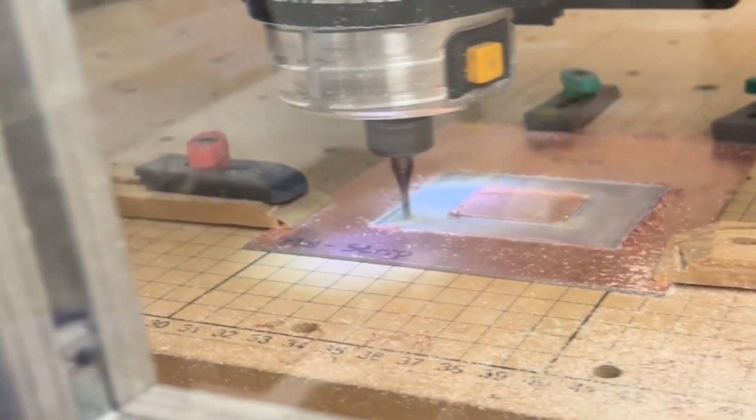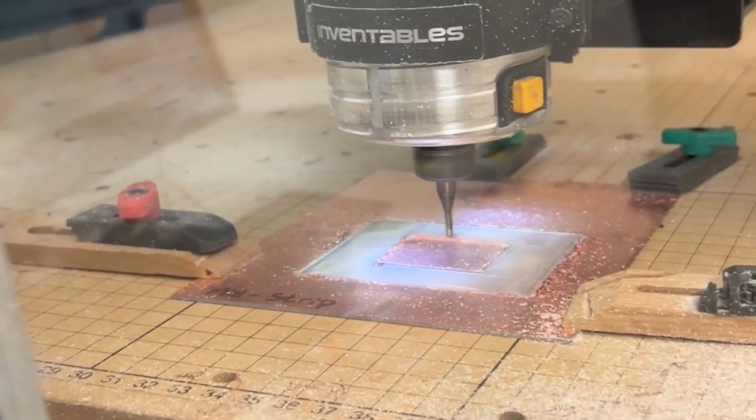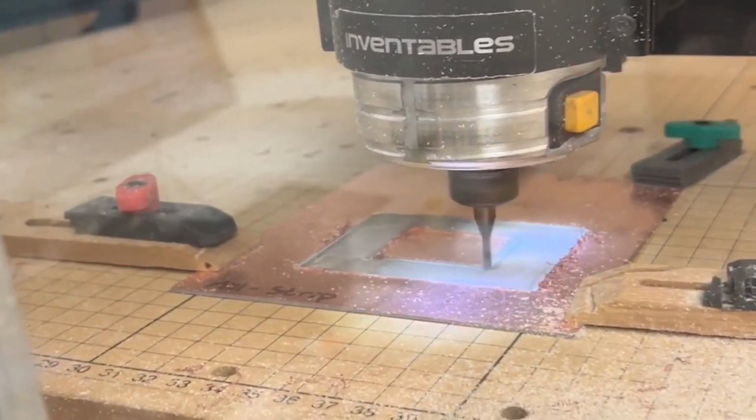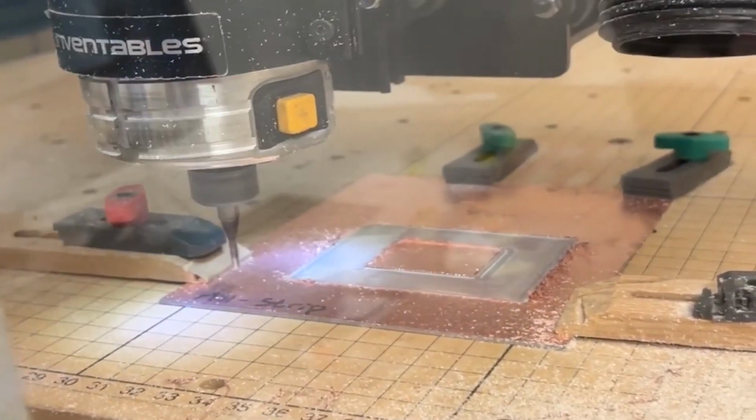Now it does a really good job. It completed the milling process successfully. The part here that I wanted to show is the troubleshooting process, rather than trying a bunch of times until it worked perfectly with 0.1 or 0.2 millimeters, which is the ideal sort of part. The issues can be uneven sacrificial boards underneath, uneven clamping, potentially a different bit that was required, and many other issues that are commonly encountered when using a mill.